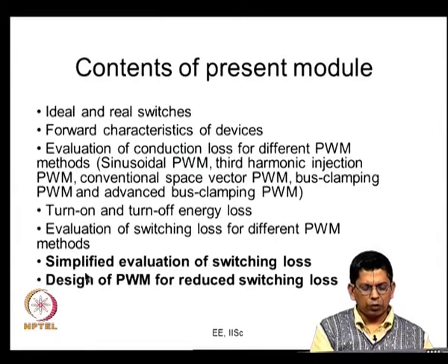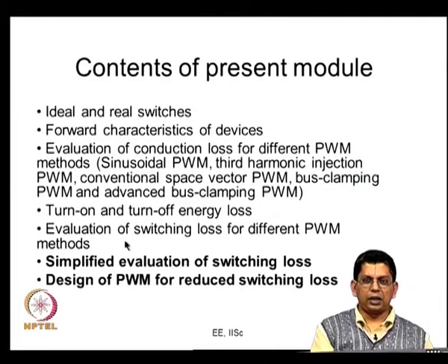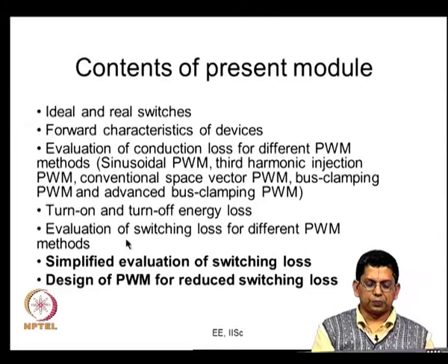That was based on the turn on and turn off energy loss, which is a function of the operating conditions. For example, if a device is turning on, there is a certain DC bus voltage, a certain amount of current that it has to conduct, and it is operating at some temperature. All this would decide how much the turn on energy loss is.